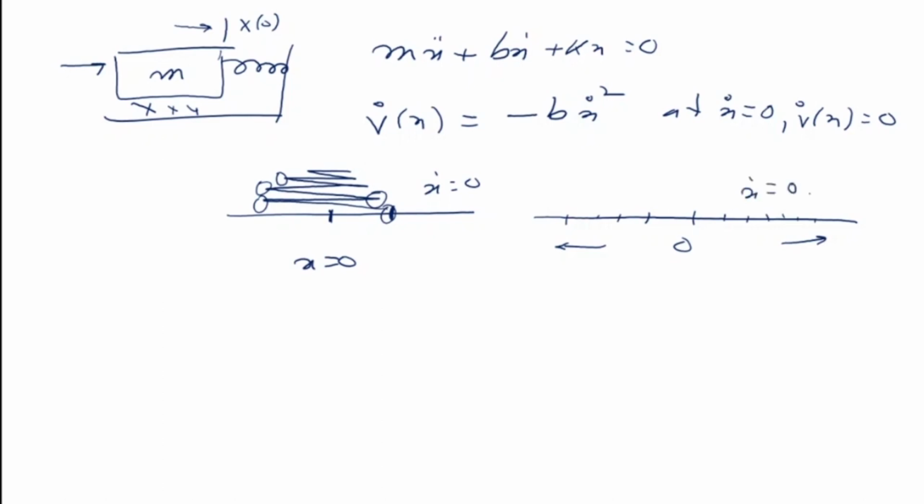Now what the LaSalle's theorem tells us, okay, before we go, there's another case where this happens. If you look at an inverted pendulum, this is my inverted pendulum. It is swinging from one end to the other end, here and here. Okay, so it is going from here and it is going back there. Now at these two locations, here and here, again your theta dot will become 0.